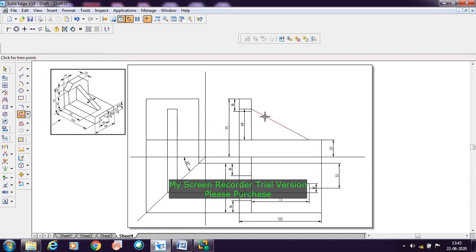This is about the visible portion of the object, and this portion is not required here. It will start only from this level. Then this is the visible portion which we got, and then here is a chamfer. Here is a chamfer for 16 and then 16. I need to go with the chamfering, so go with the chamfer here. Take the edge and then take this edge. You need to give the 45 degree setback A as 16 mm, and then setback B as 16.